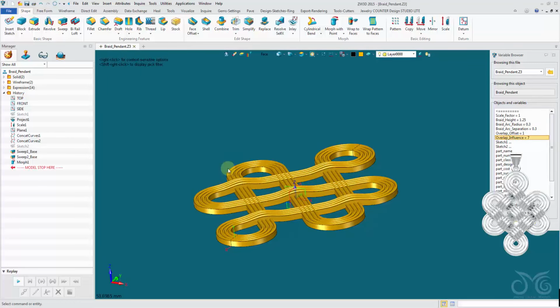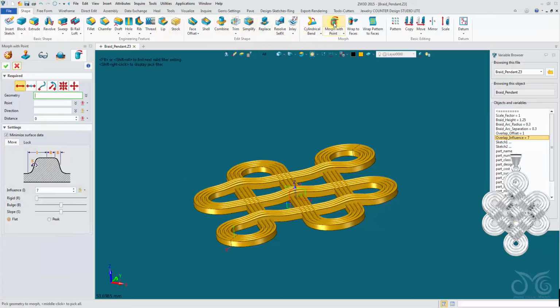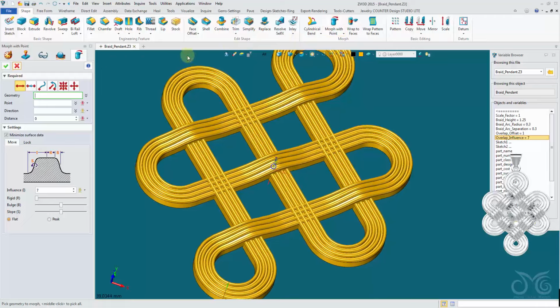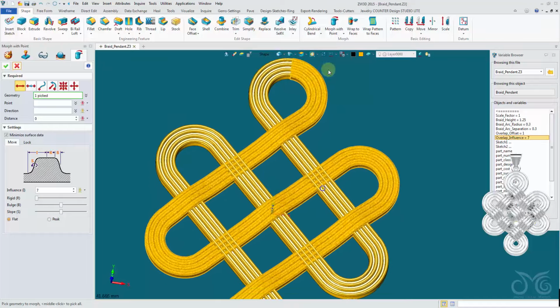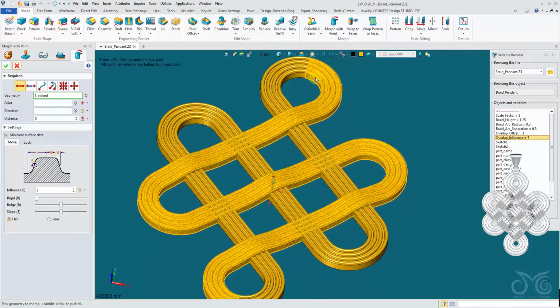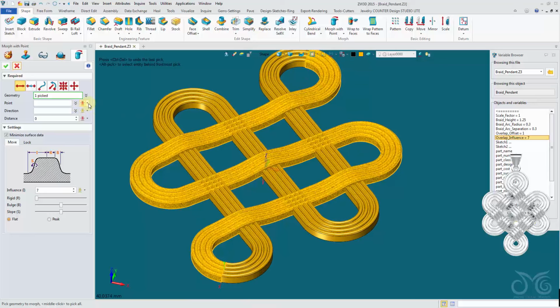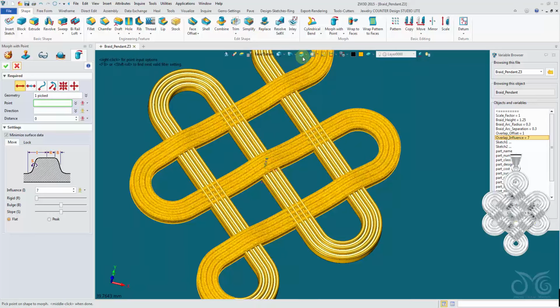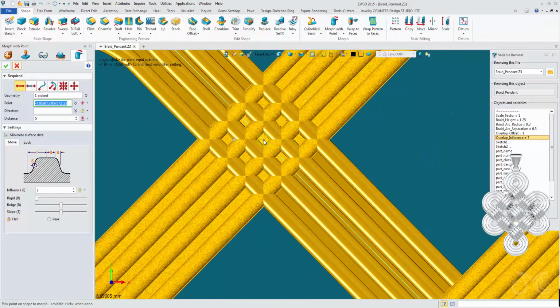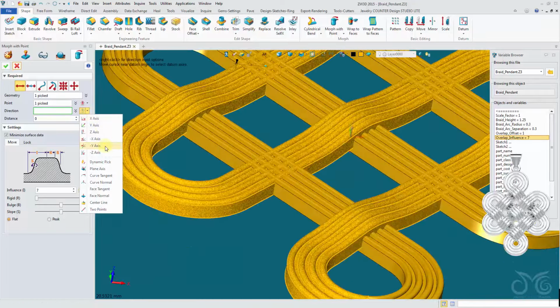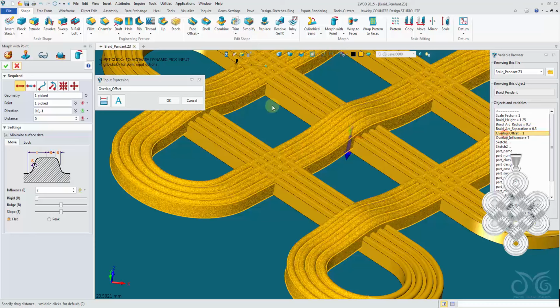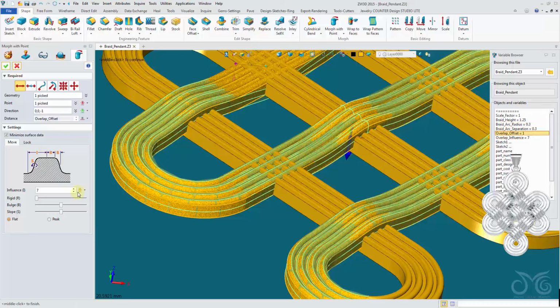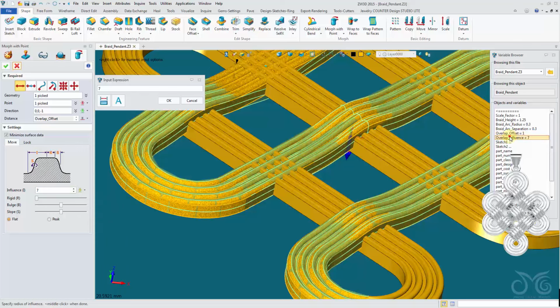Okay, and we'll morph some more now. Morph with points. The geometry, let's pick the same shape that we just morphed. Okay, now let's do a negative morph. Okay, so the point, you know this part we need to do negative, so the direction, negative Z, distance, expression, overlap offset. There you see it go down. Influence, let's link this up to the expression, overlap influence. Okay, we had 2 values pop in, just need 1.